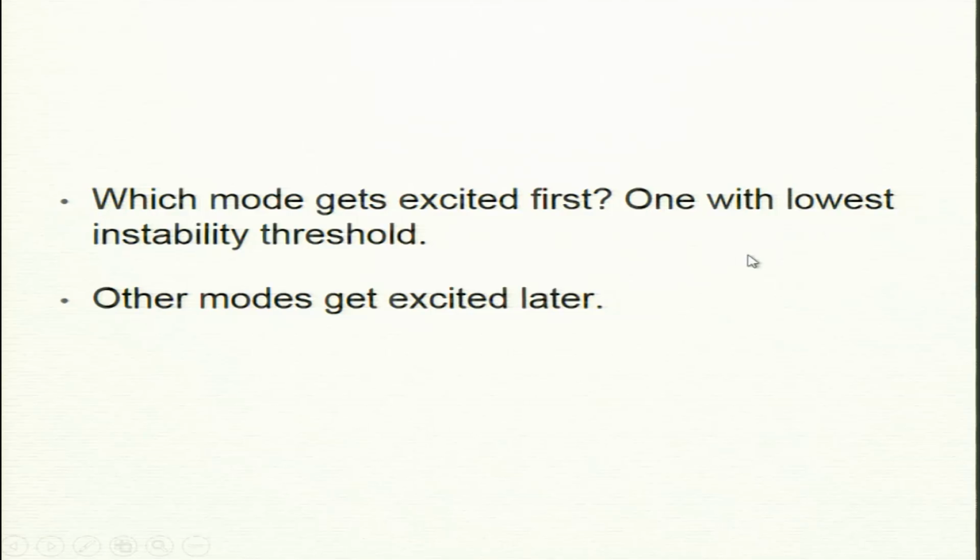So, how did I get that? My parameter was k perp, and I varied k perp and saw that Rayleigh critical was lowest for some particular k perp, and for our problem it was pi by root 2, that is kc. Okay. So, we can see among Fourier modes which become unstable, but if I increase my temperature or Rayleigh number, then other modes also get excited later. So, we will get a mixture of modes, but nonlinearity is also not going to sit there.